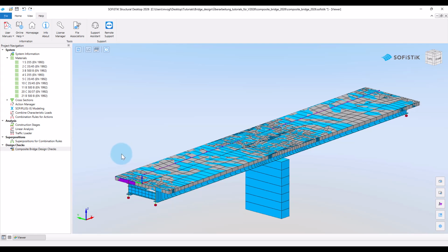However, this action is not the only relevant one for calculating the stress ranges in the section. For calculating the effects of the loads from the fatigue load model, it is important if the composite section is cracked or uncracked, or framed differently, if the concrete in the section is subjected to tensile forces or if it is in compression.